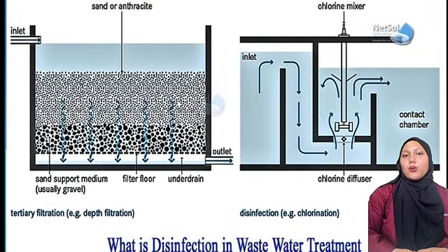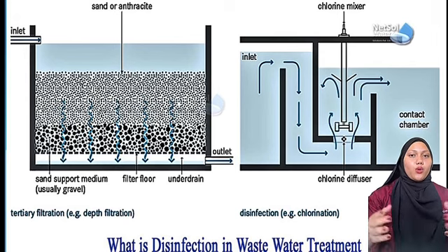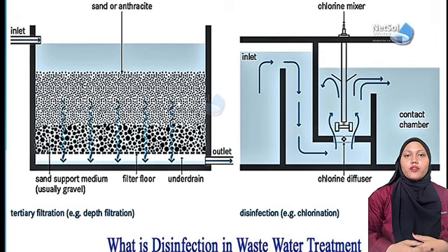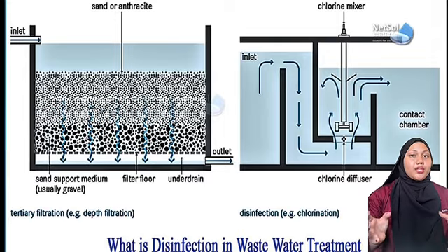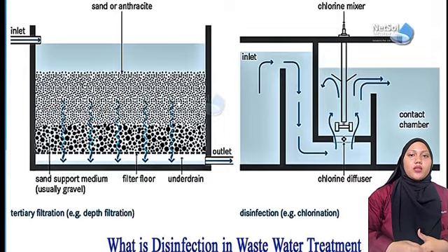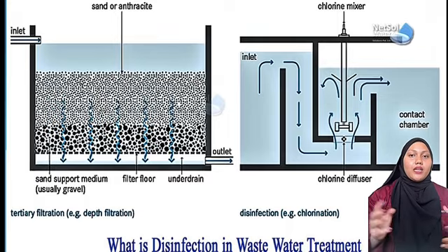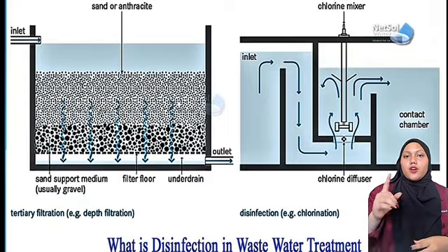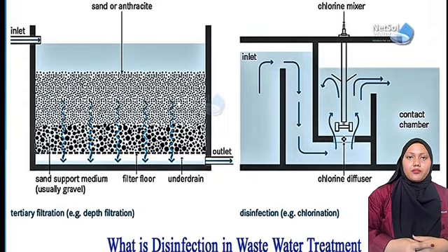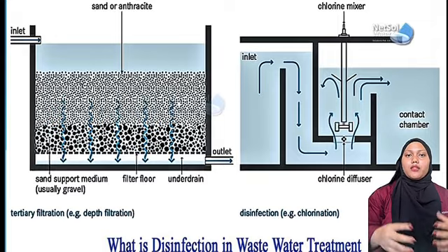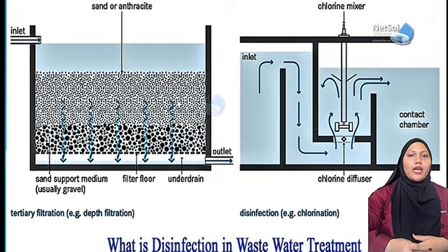Now, let's look at filtration. In Johor, after large particles are removed, water passes through sand filters. This process removes fine particles, dirt, and suspended solids. Filtration improves water clarity and reduces the need for excessive chemicals later in the process. From a sustainability perspective, this is beneficial because it minimizes chemical usage and improves efficiency.